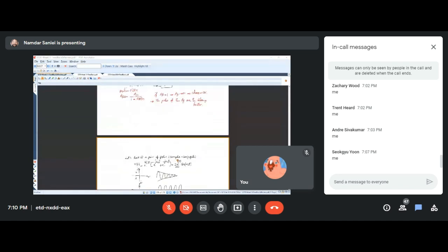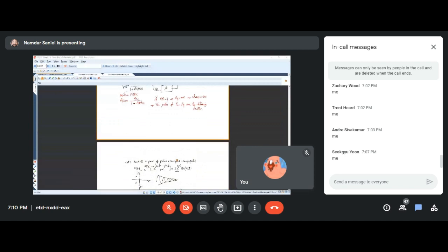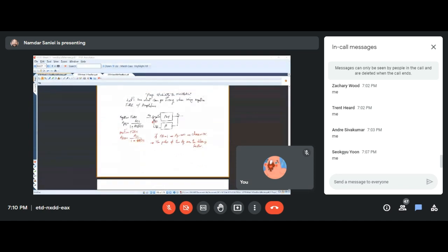So basically, this is the denominator that causes that. You see, this negative here screws things up. However, 1 plus something which is positive itself can never get 0. That's why negative feedback guarantees that you have a stable system, not chaotic.